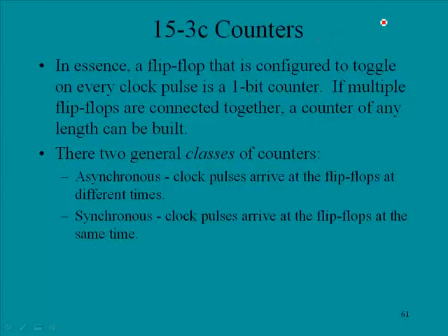Okay, we're continuing in 15.3 and we're looking at the subject of counters. In essence, a flip-flop that is configured to toggle on every clock pulse is a 1-bit counter. If multiple flip-flops are connected together, a counter of any length can be built. There are two general classes of counters.